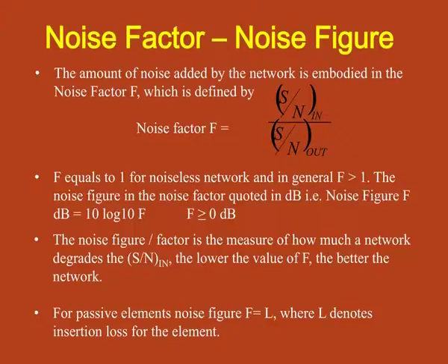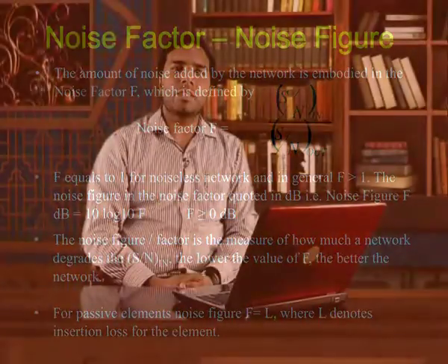Typically, this noise figure is defined for a temperature of 290 degree Kelvin, but your systems can operate at varying temperature ranges. For satellite communication, for example, the temperature range can go from -10 degree centigrade to 55 degree centigrade. So, we need a characterization for noise which will allow us to translate the noise characterization at 290 degree Kelvin in terms of noise figure to something more relevant to the operating temperatures. For that matter, we define what is called equivalent noise temperature.